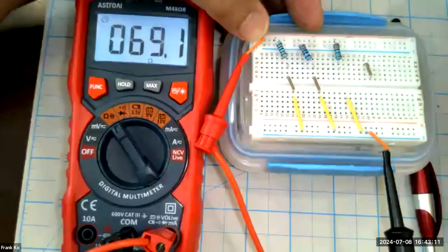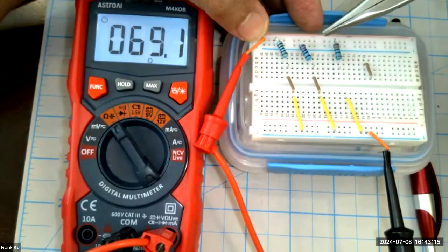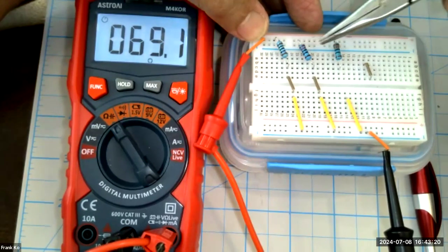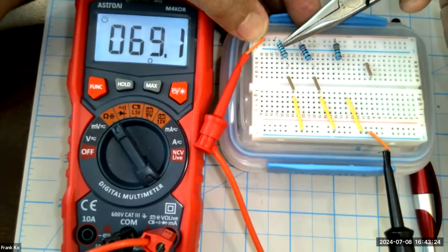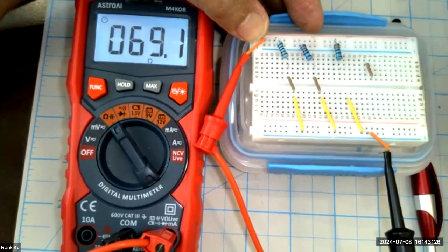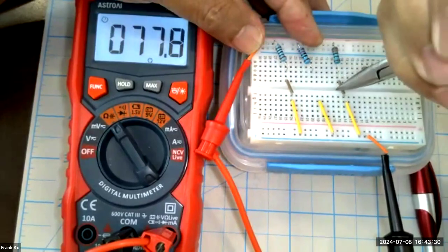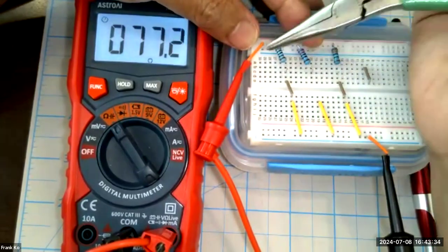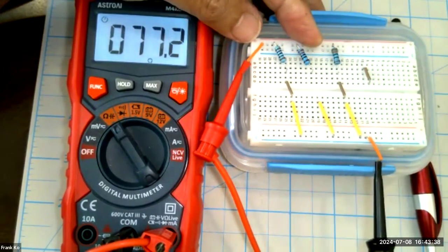What's your second calculated value? Your second calculated value was to calculate R1 parallel with R3. First was R1 parallel with R2, presuming something was wrong with the third resistor. Now we're going to calculate R1 parallel with R3, presuming something's wrong with the second resistor. So what I'm going to do is I'm going to move this jumper over to here. I have to rebuild this. So R3 is back in the circuit, R1 is back in the circuit, but R2 is clearly not in the circuit. What did you calculate?